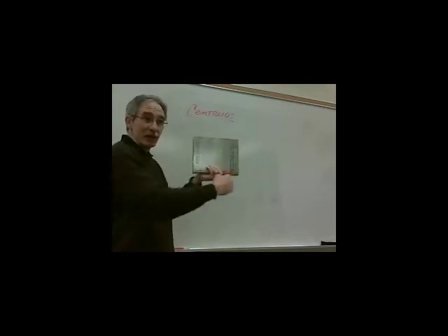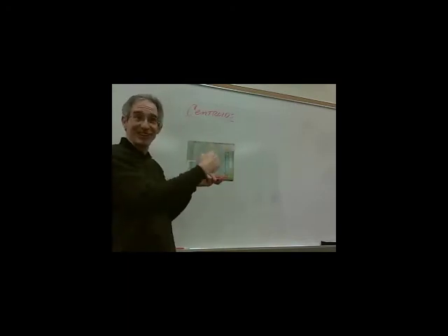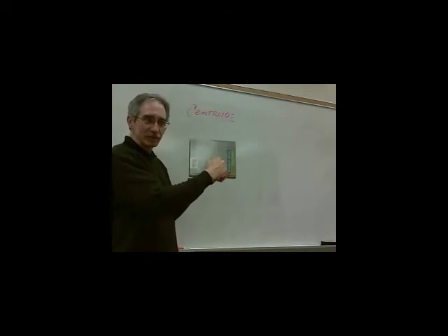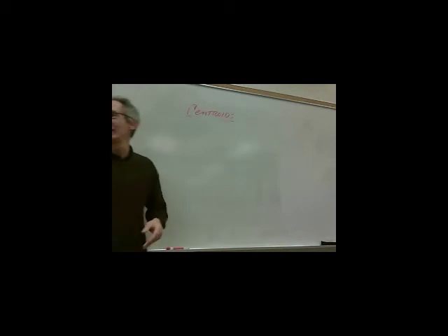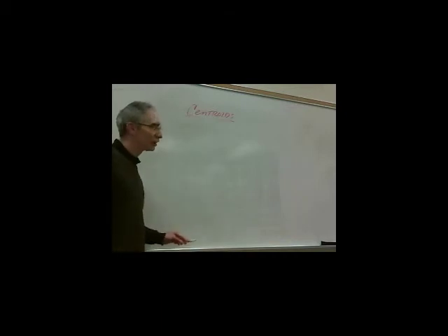In 2 dimensions, which is what we deal with, that point is called the centroid. So again, you might be confused with some of the language that we use, centroid, center of gravity. They're both related to each other, but one's a 3-dimensional aspect, center of gravity. The other one's a 2-dimensional aspect, centroid. So we'll deal primarily with centroids.